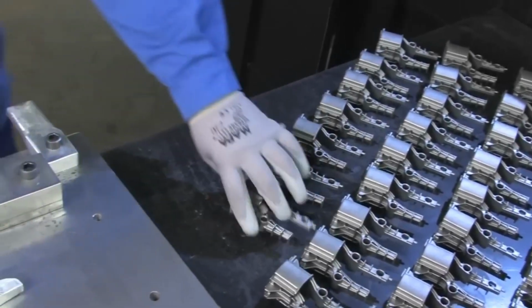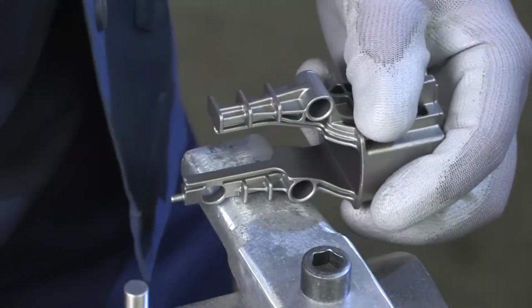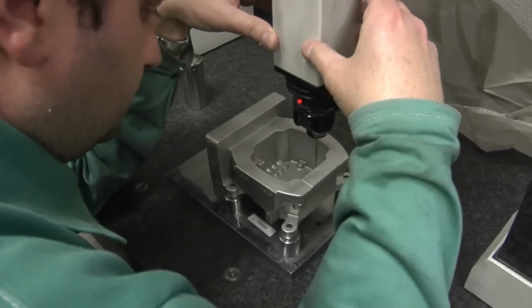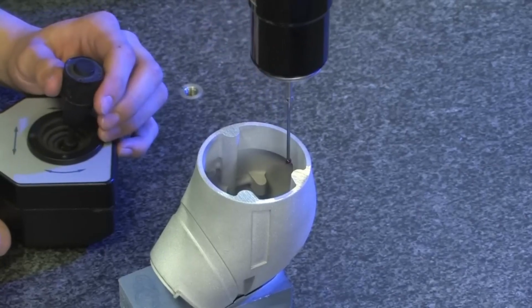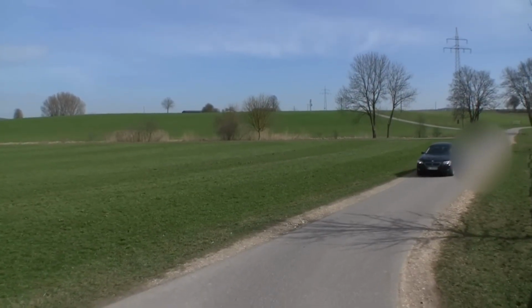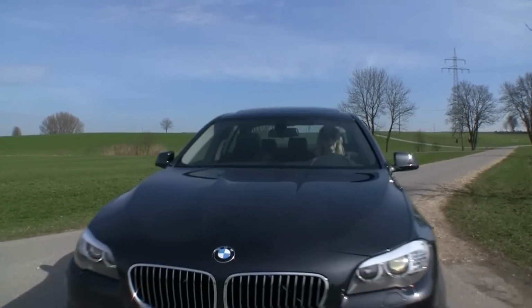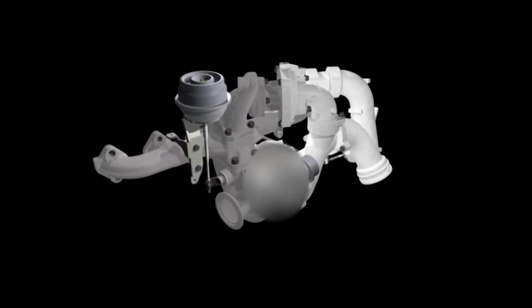Different wall thicknesses in one casting can be easily and precisely realized in investment casting. The designer can precisely adjust the geometry and material thicknesses of the casting to the requirements of the application and optimize the material use. Here is another application. Extreme demands on the durability and precision of the casting are made by the automotive industry. Strict emission standards and fuel-efficient engines, combined with increasing engine performance, have led to the achievement of the turbocharger. Investment cast flaps control the aggressive exhaust stream, heated to over 1000 degrees Celsius.